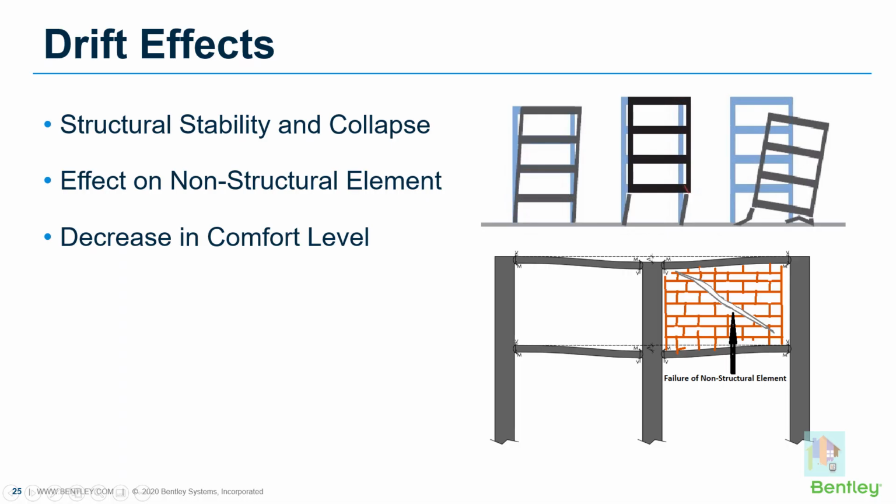First of all, higher drift can cause serious structural damage if not considered properly in the design stage. If a floor shifts horizontally and columns are not designed to resist that movement, then obviously cracks generate, and in severe conditions, structural collapse. Another important aspect is the protection of non-structural elements like glass or partition walls.